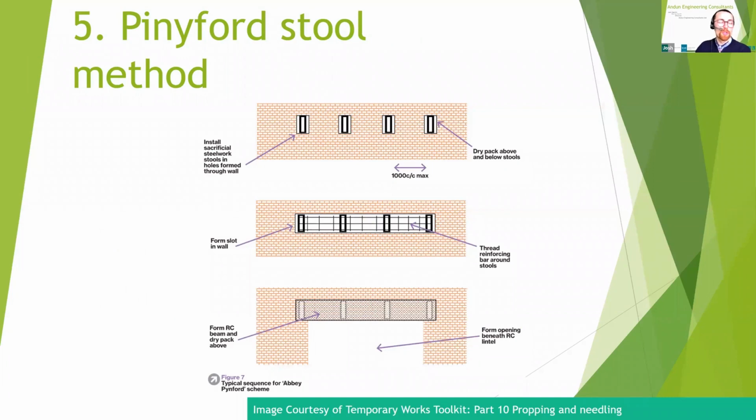The Pynford stool method. This is a method of casting an in-situ beam into a wall over a proposed opening. The illustration shown here has been taken straight from the Temporary Works Toolkit Part 10, which is a series of articles that are aimed at assisting the permanent works designer with temporary works issues. It's a great document. I'll come to that a bit later.